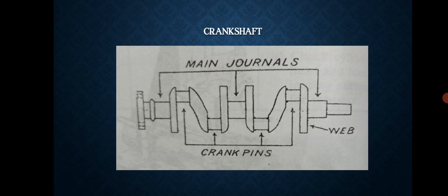Next is the crankshaft. The crankshaft is a one-piece casting or forging of heat-treated alloy steel that is of considerable mechanical strength. The crankshaft takes the downward thrust of the piston during the power stroke. The power exerted by the piston through the connecting rod against the crank pin on the crankshaft causes the shaft to rotate. The crankshaft generally has drilled oil passages through which oil can flow from the main to the connecting rod bearings.